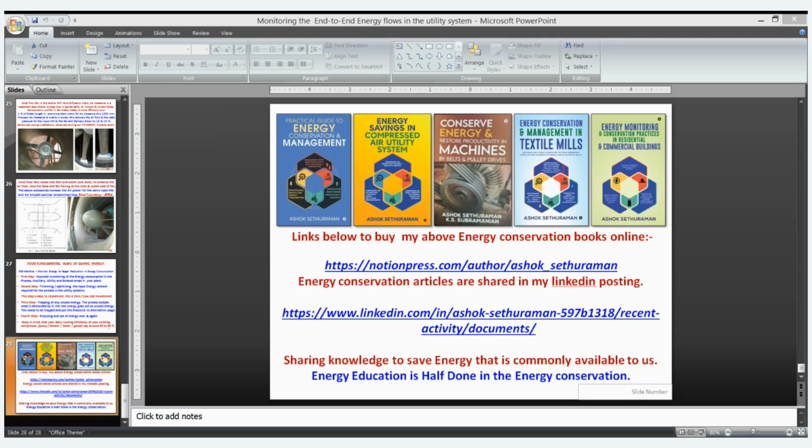Yes, sir. Mr. Sethuraman, good afternoon. It's a wonderful presentation. Two things you can add. One, heat recovery. Then there is one more thing in the compressor, optimization of oil flow. The compressor has been designed for a certain pressure and certain ambient conditions. But most of the clients use it at lower pressure, and ambient is also low, load is also low.